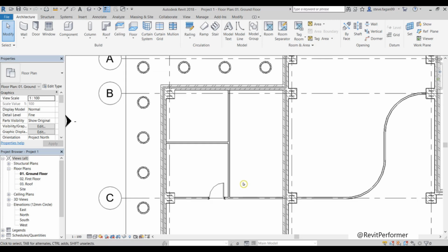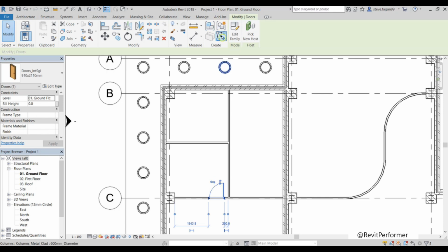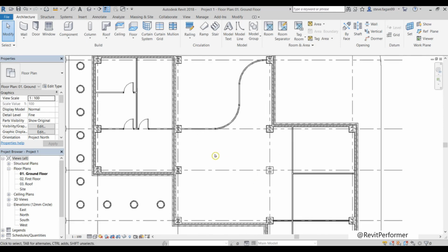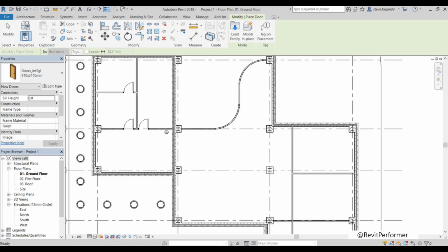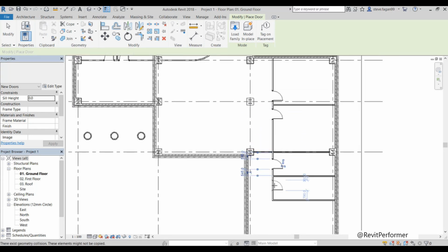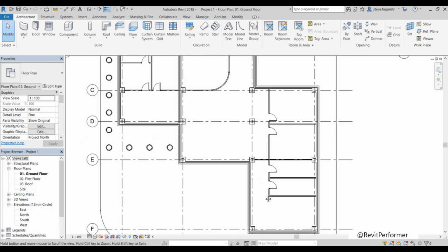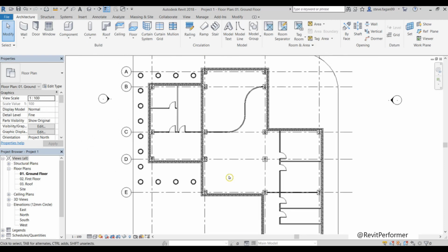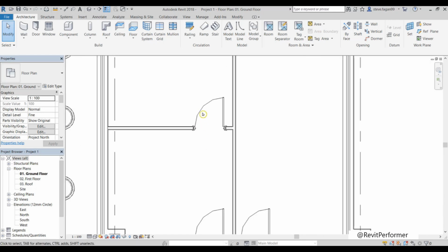So we have two ways now we can go back to insert those doors. We can either select the door, use our create similar, or we can also use our door tool and it's the last selected, so we can just go and place. It's best to just place the doors and then afterwards we'll come back and adjust their position. So once we have all of those 910 doors placed, we'll then just place them more accurately.